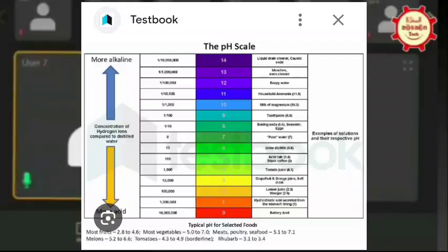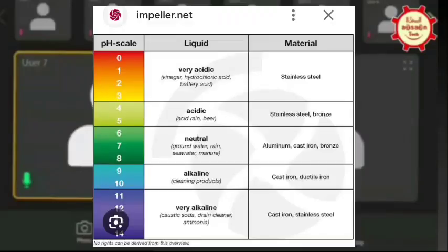So that's where the role of the corrosion engineer, materials engineer comes. That person will use his experience and knowledge to select the material. I'm cautioning you, don't just go by the curve, because the environment you are using, saline water or water with chloride, and the environment where they have tested are different. The testing is done in a very highly corrosive solution, acidified 6% ferric chloride. So if they say 35, it can go even up to 70. The charts show relative resistance, but you cannot exactly interpolate. You can approach a materials and corrosion engineer for selection.